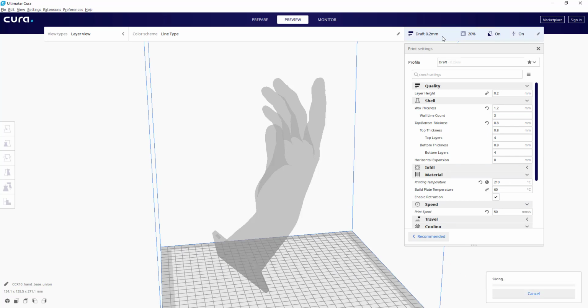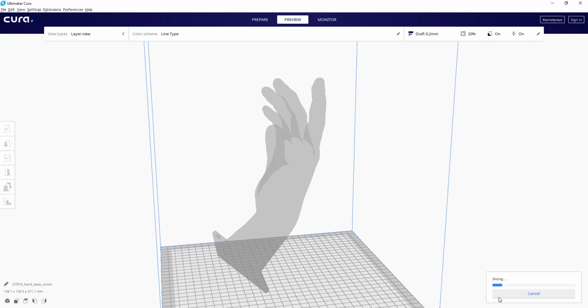If the layer height were 0.1, the maximum quality of the printing, here we will set instead of 0.8 around 1.4 or 1.2. 1.2 will be fine. I very often print at 0.2 unless I need an excellent quality.